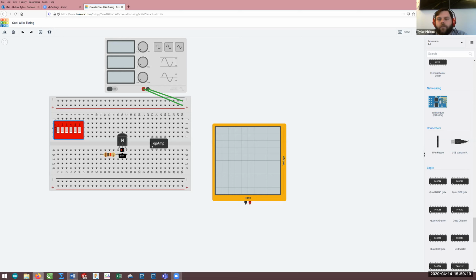And I will be glad to share any data sets. We have a Tinius-Olsen 60K tester in which we can pull apart samples and crush concrete samples too, and I can provide the complete stress-strain curves for those. So if anybody has materials they want, I'll be more than happy to pull those apart and provide any data set you'd like.